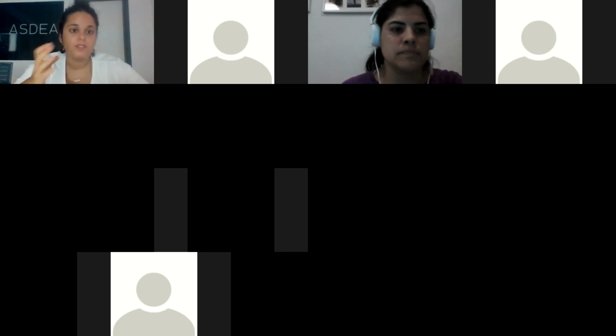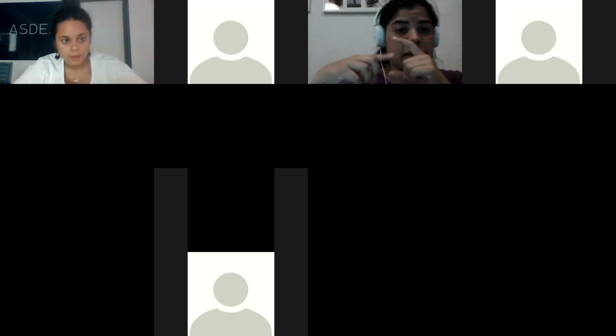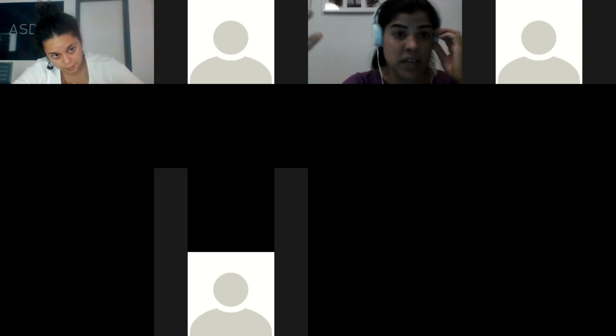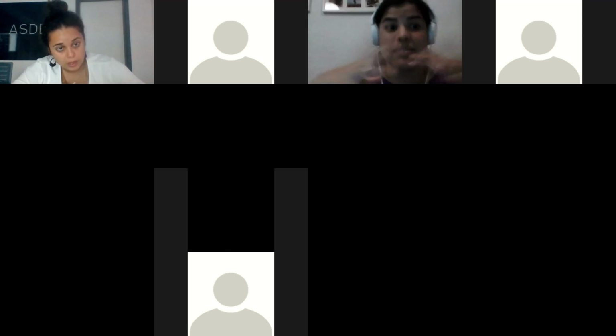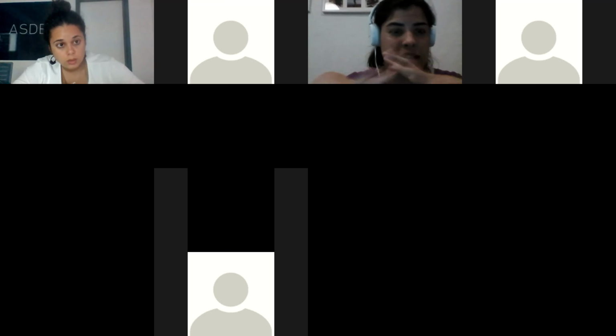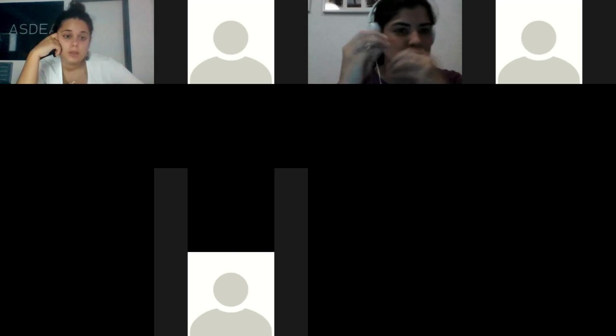Thank you. Refine it, but we noticed that it's better. Yeah, the thing is, if I refine too much the shell I have, I get an error that I don't have enough space to run it. Someone said it's because the mesh was too fine.